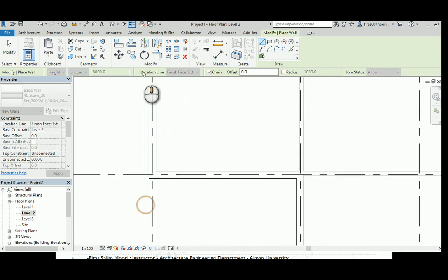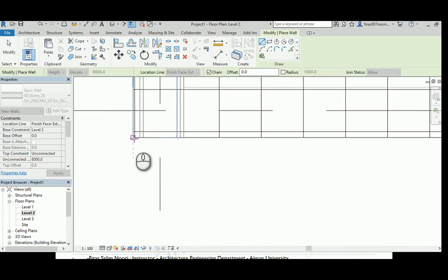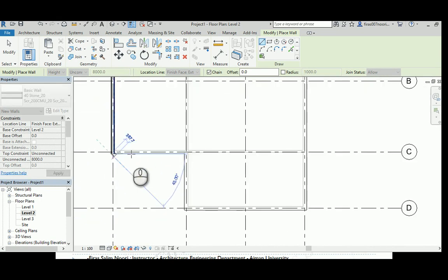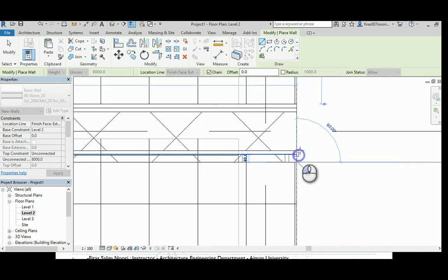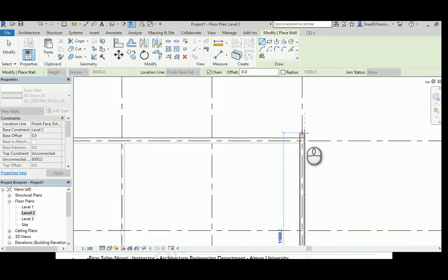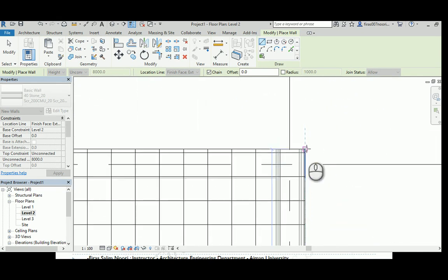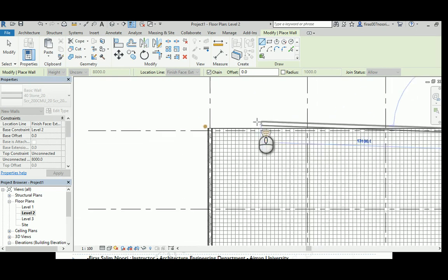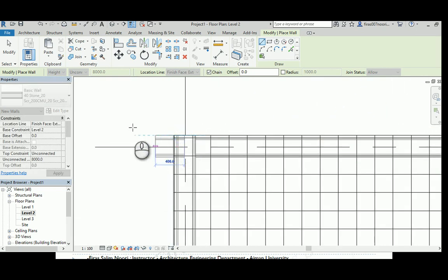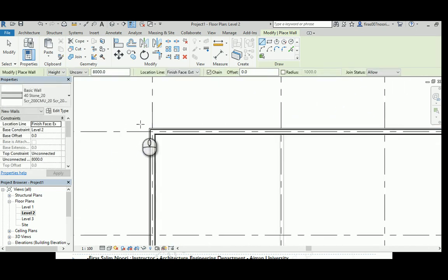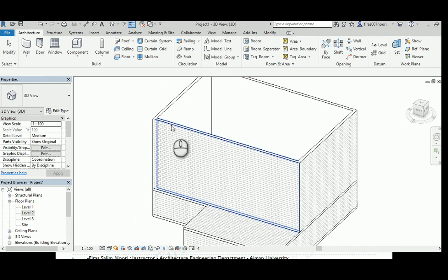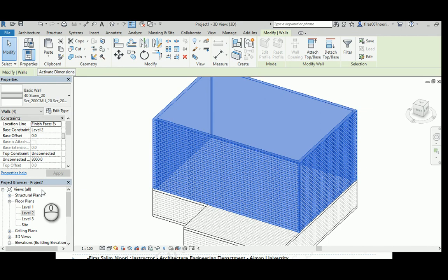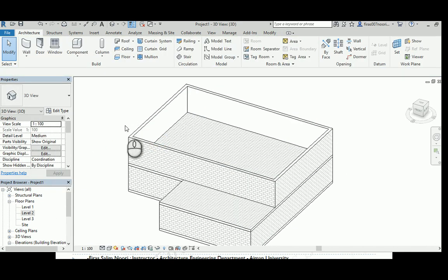So now click to the endpoints. Careful of your clicks. Click here, because we don't want to select any of the hatches available for the slab. And finally here, lovely, isn't it? And same, we're just going to select those 3-4 walls by hovering, and then click, and then select attach to the top of this level, and that's it.